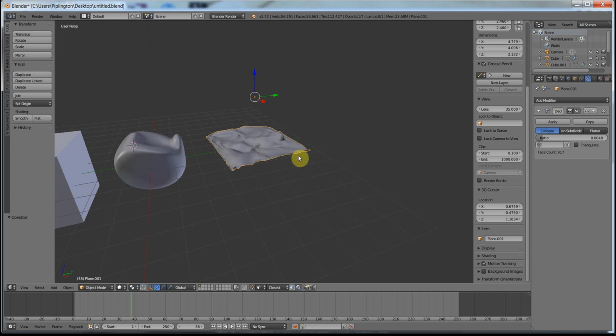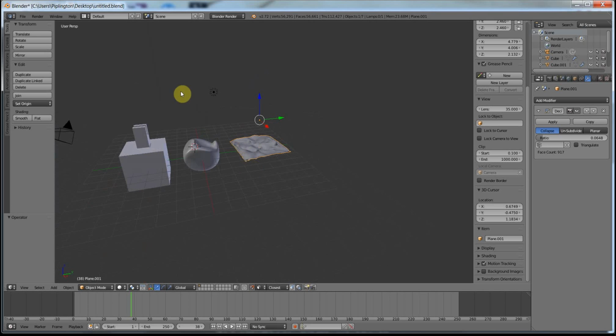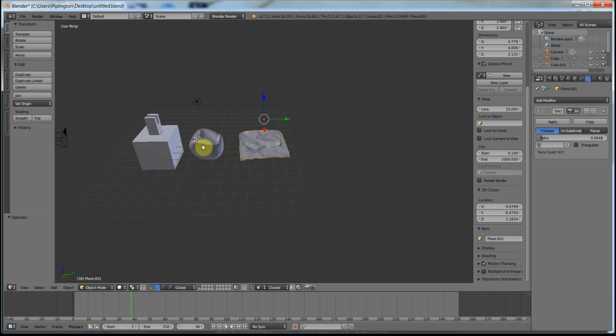And ZBrush and things, they have the same kind of automatic remesh tools, which can get your shape to low poly. But for things like, I modelled some hair, some mesh hair, and I made a high poly model in ZBrush, and then I used the automatic remesh in ZBrush, and then I fixed it in 3ds Max, just the same way that we would be merging things together and deleting a few vertices and all that, and then you can bake down.